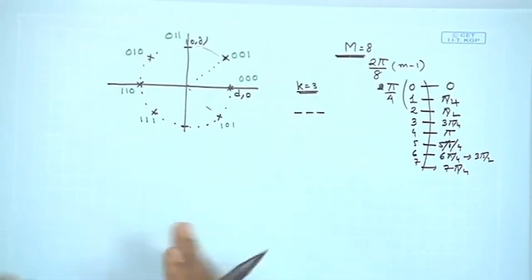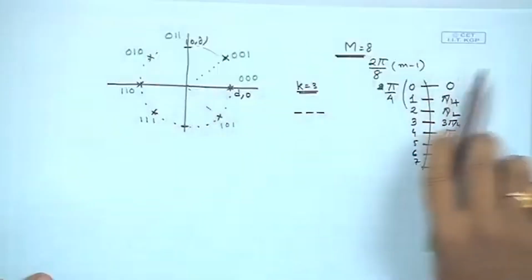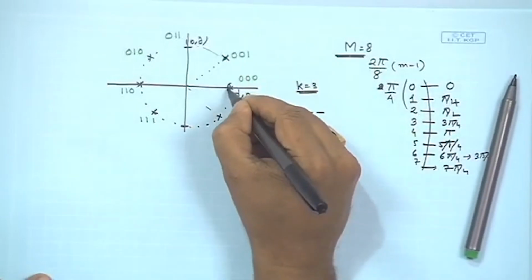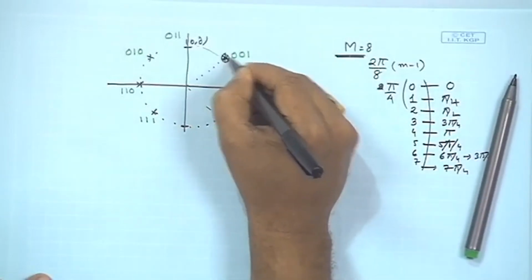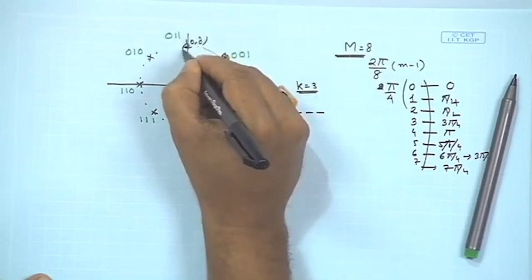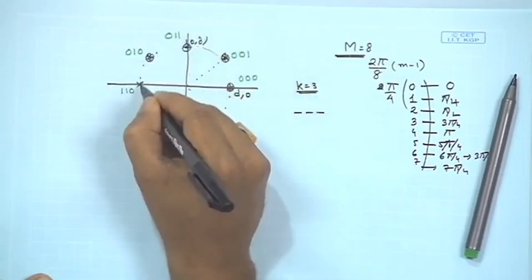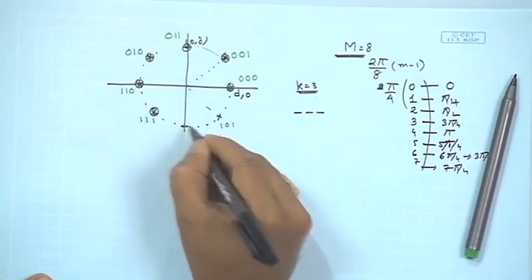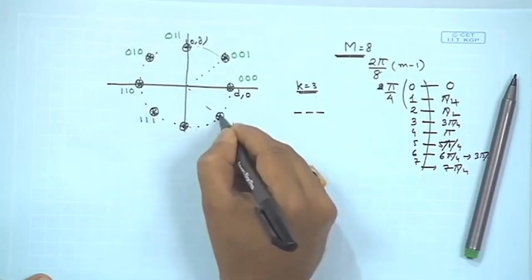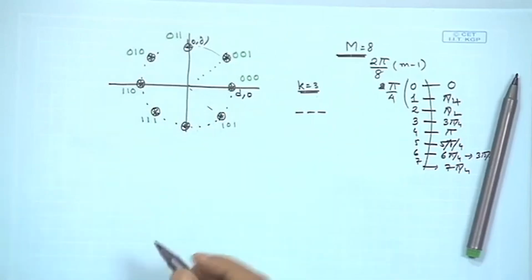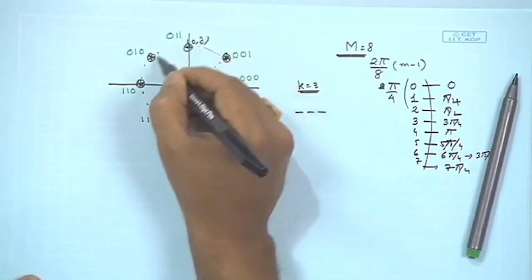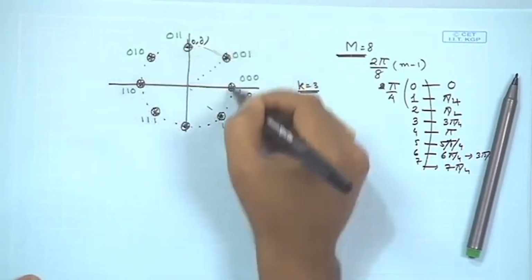What we could see here, the difference between the analog angle modulation and the digital modulation scheme is, if we look at this particular diagram, we have only a fixed set of angles to select from, and we will be choosing only these angles based on the bit sequence and not a continuum set of angles, whereas in angle modulation, in phase modulation in analog communication, you are selecting a continuum.